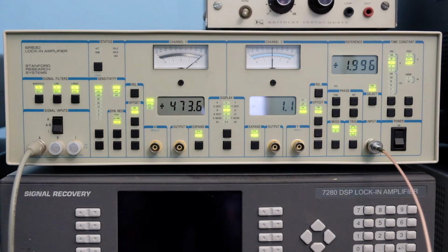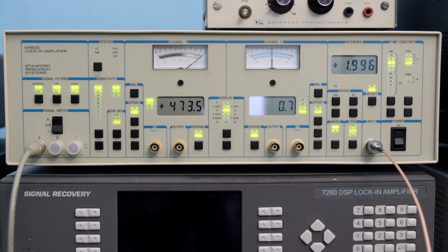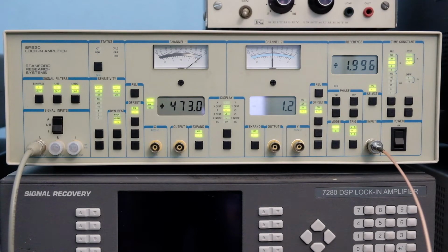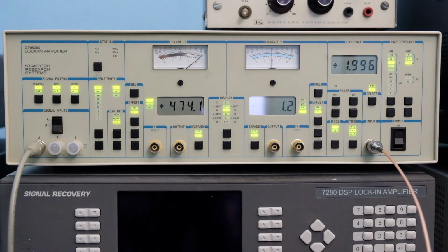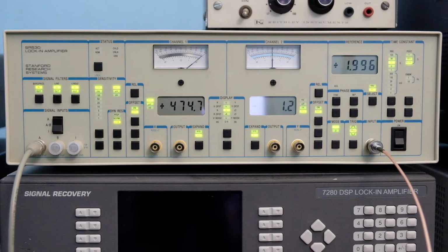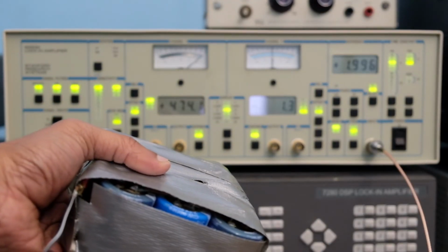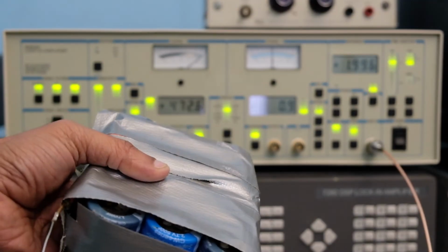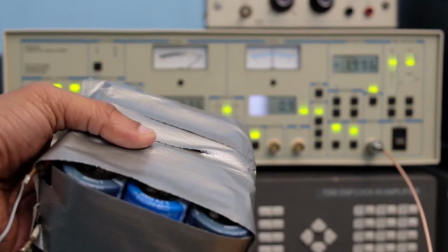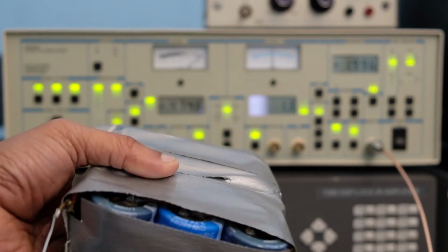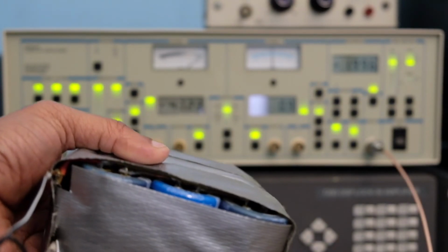So my last experiment is going to be to try and measure the ESR and capacitance of a supercapacitor. I don't expect it to work because I cannot go low enough in frequency to actually do this. I did some calculations to figure out how much I would need to go down to reasonably measure the capacitance, and I would need to go to like 10 millihertz, which is well beyond the range of this particular lock-in amplifier. And the capacitor is really this bunch of 500 farads in series, a 12 volt supercapacitor, which has an effective capacitance of around 83 farads.